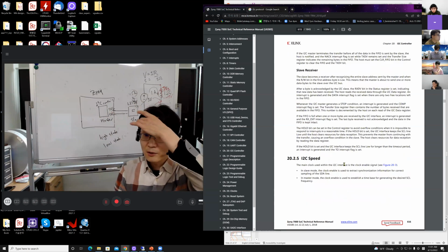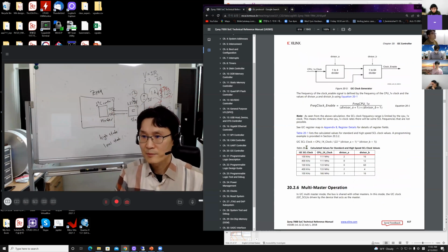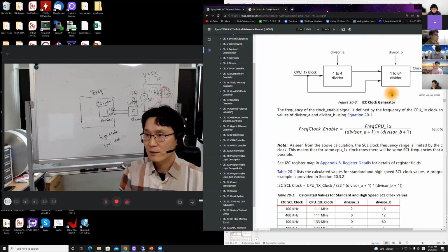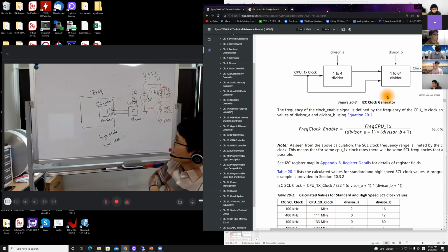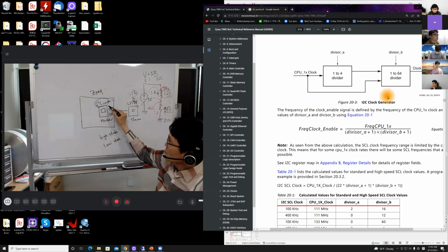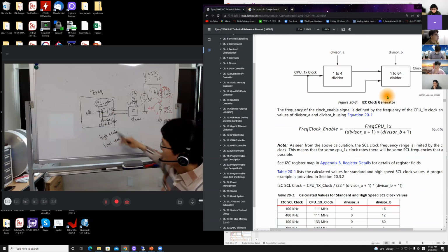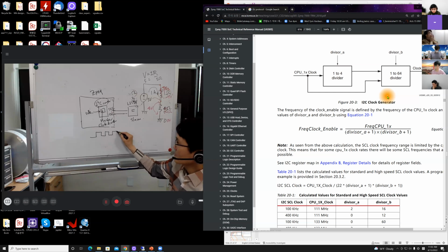That is talking about the detailed operation, and then some detail about clock frequency. What frequency do you want to use? The I2C frequency. So using a clock divider inside this hardware module. This one is the clock divider. So you have an incoming clock, right? ICLK, for example, the incoming clock. The clock is running pretty fast, for example.